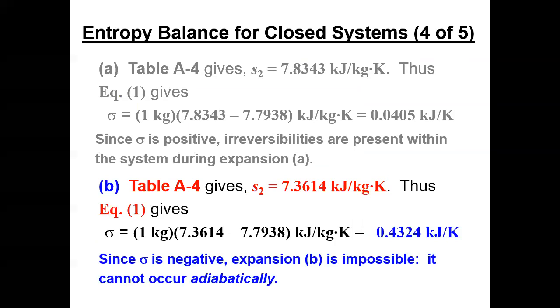It has to. That's what the properties say. Well, in this case, it was positive. So the combination of those terms has to be negative, and the only way that can happen is for the heat transfer, because the production term at best can be zero, and in a real process it won't be zero. It will have a positive contribution. So you have to transfer enough heat so that you can make this true.